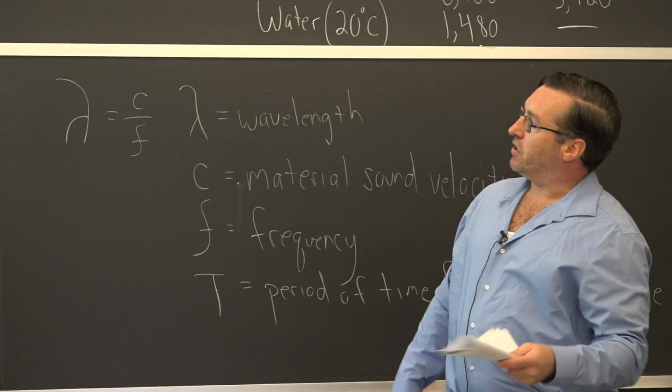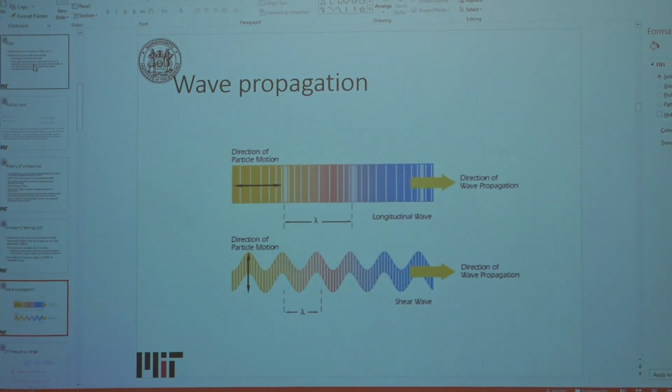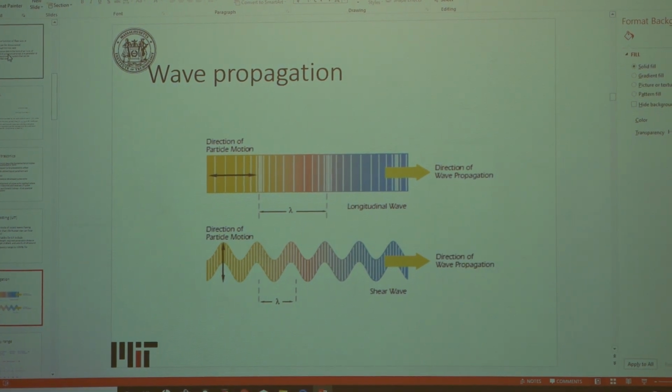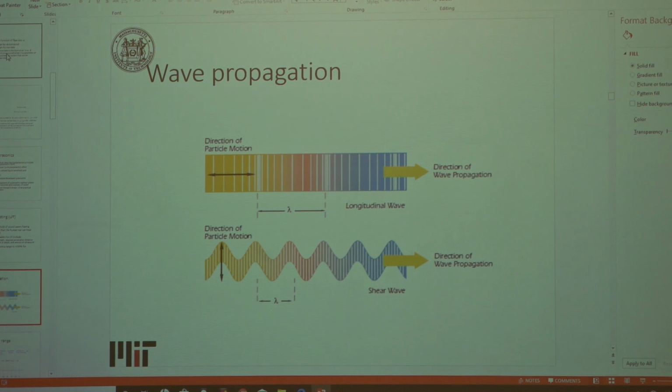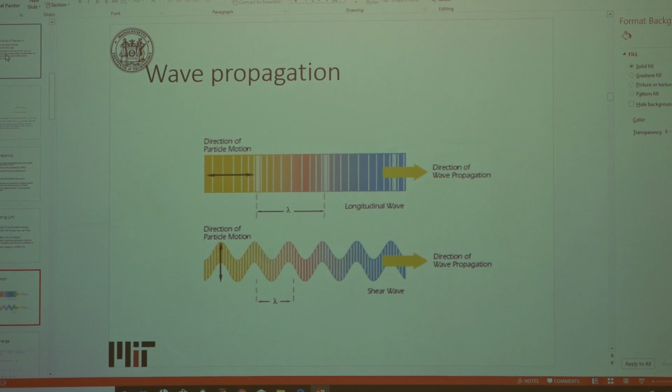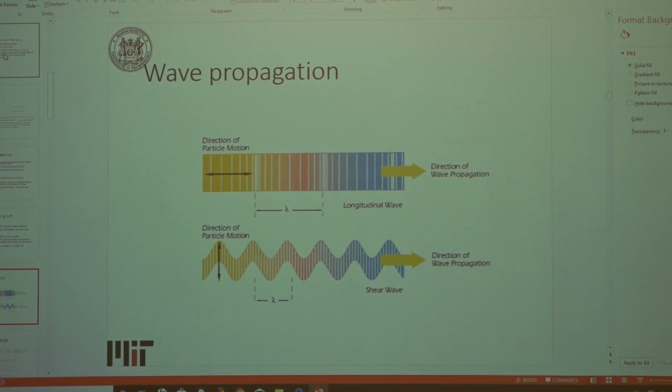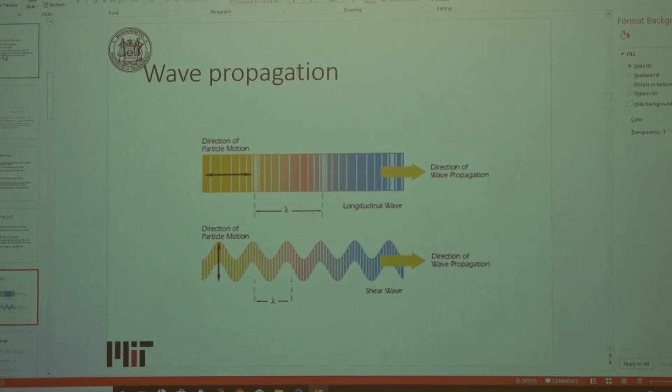To your question there, it ties back into the direction of the wave propagation. For a longitudinal scan, where you're just sending the wave straight in, it hits a back wall and comes back, that's the direction of the wave propagation. There are ways to play around with the inspections if you want to find a smaller flaw size. That's where they can tie in the shear waves, and they can use different types of wedges and transducers for the equipment to try to get more sensitivity.